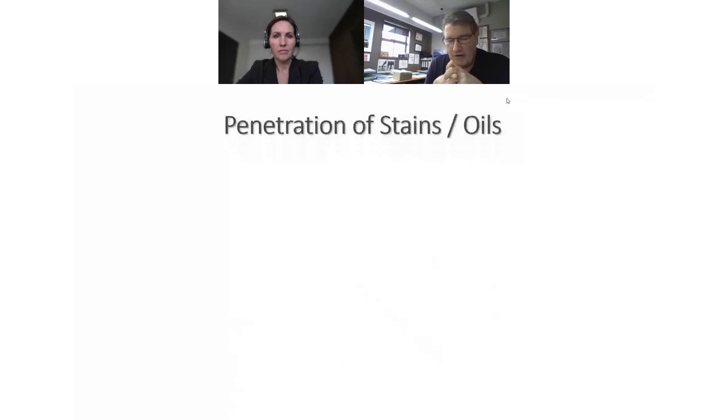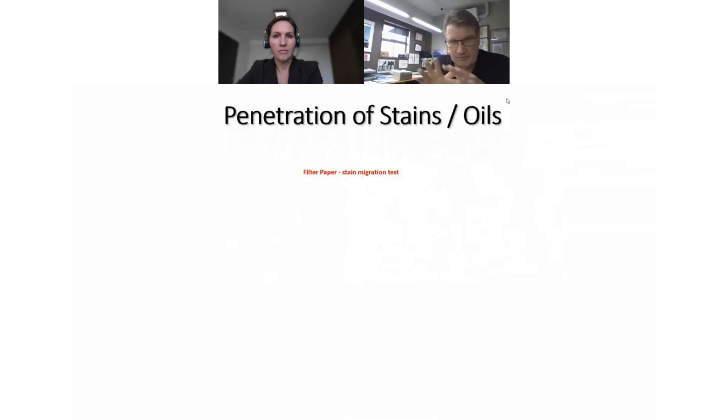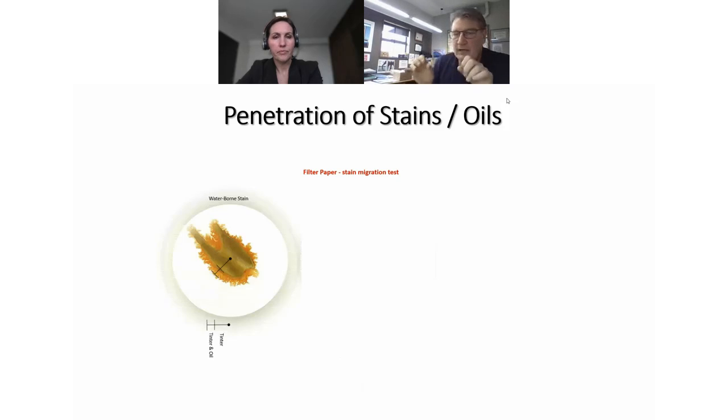Now, what I'm about to show you is for educational purposes only, and it's to try to show the difference or the penetration ability, the potential ability, of stains and oils in the market. Common ones, which I'll explain in a minute, and I use this to demonstrate to our staff. So what I've done is I get a piece of filter paper and I put on a certain quantity of our waterborne wood stain. The whole idea is I drop it onto the paper, and the paper's made out of cellulose fibers. So it spreads out, and then we see how far it spreads out and we compare it to the other ones, right?